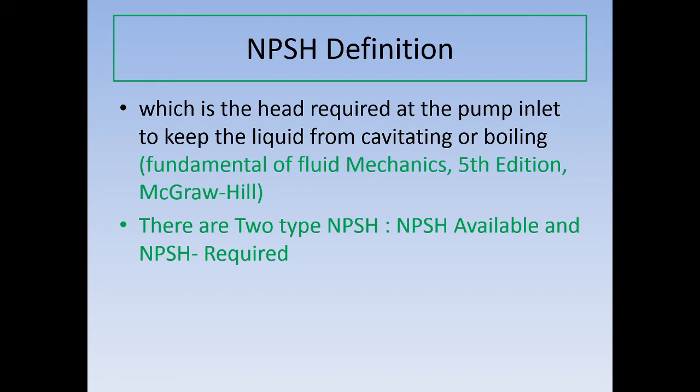So what you do, you test the pump, you open the valve at the discharge, and then you measure the flow capacity and adjust everything to meet 73.35, and after you get that point, now you want to throttle the suction valve until you finally notice that the discharge pressure of the pumps reduce 3%.